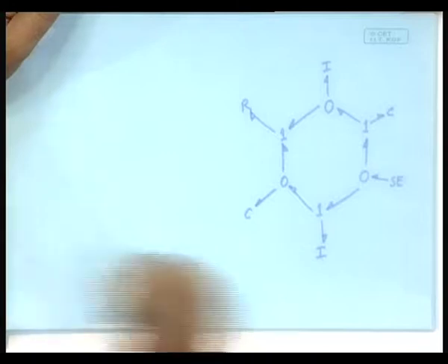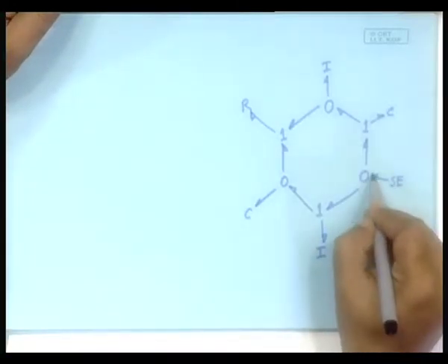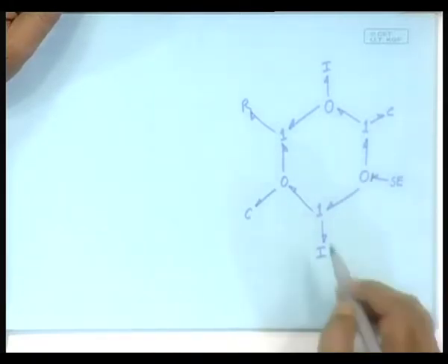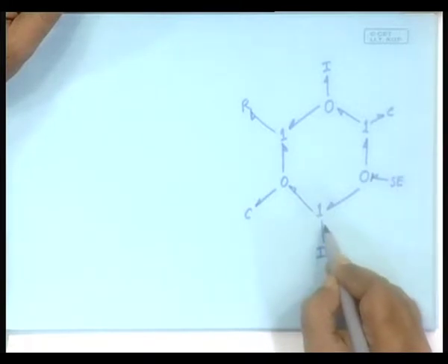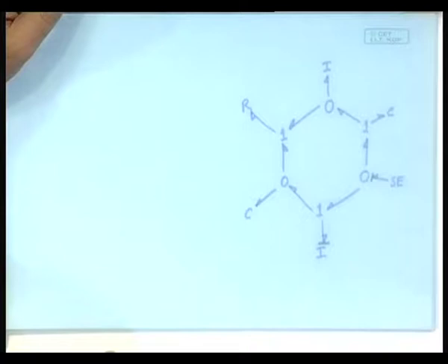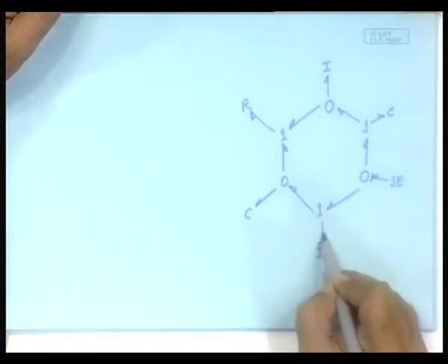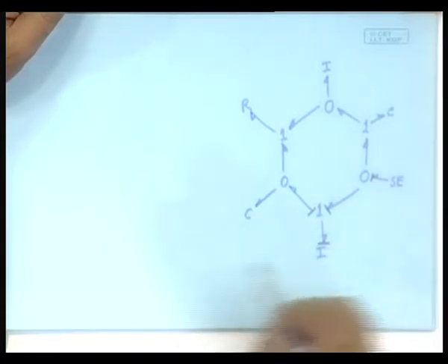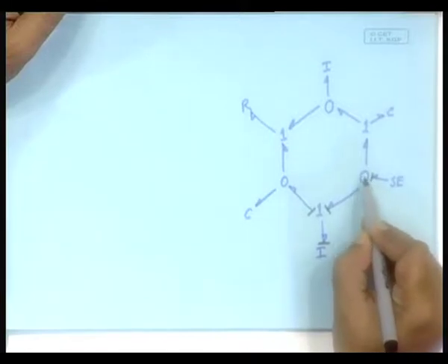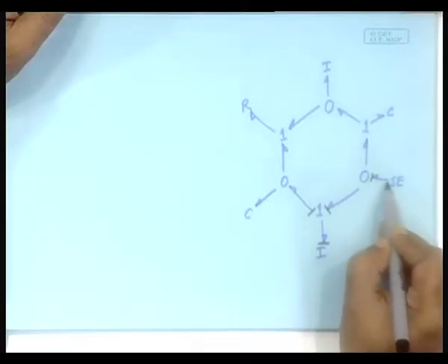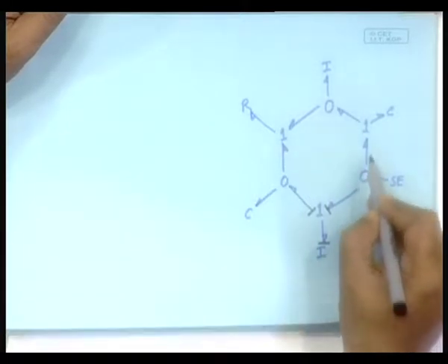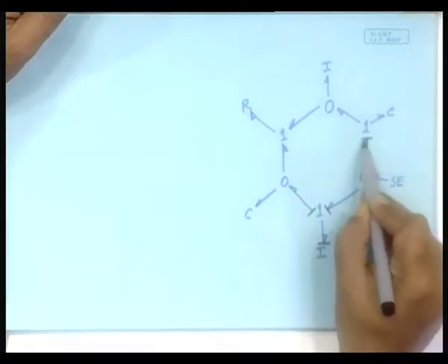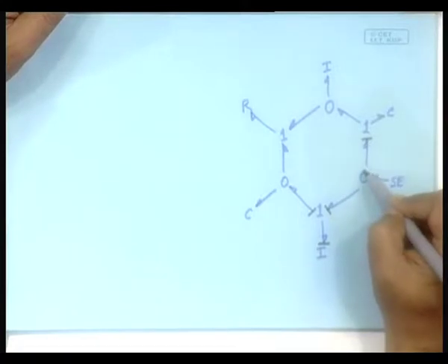Let us put the causalities. Start with SE. Its causality is like this. It gives the effort information and receives the flow information. This I element, its natural causality is like this. The moment it gives the flow information into the 1 junction, the flow information must be taken out, right. So, now this 0 junction has received the effort information, and that is why it must distribute the effort information like this. Okay. So, it gives the effort information in this direction and receives the flow information in this direction.